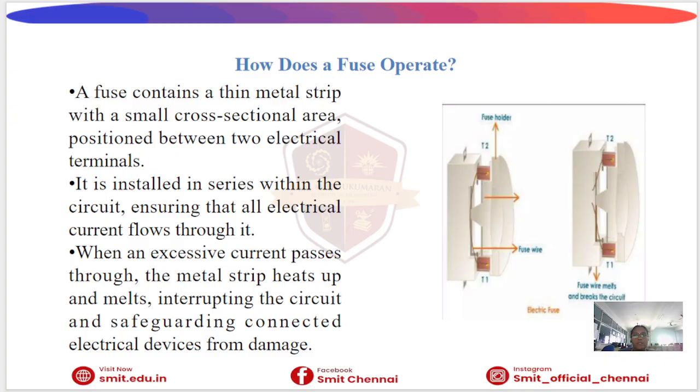Next, the working principle of a fuse. A fuse is connected in series with the circuit. When normal current flows, the fuse element remains intact. When overcurrent or a short circuit occurs, the element heats up and melts, breaking the circuit and stopping the current flow. So this protects the electrical equipment from damage.